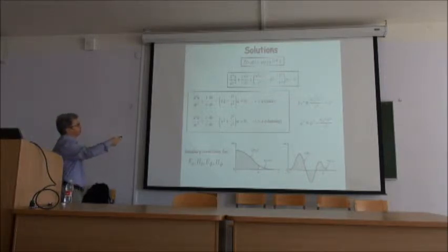And in this equation, if I look at these two components, inside the core or outside in the cladding, we see that this number is going to be positive inside the core, and I define that quantity here, which is just the difference between these two terms. Outside, these two terms will be negative, so I actually define it as the reverse, as this alpha squared. Then I use those variables here instead of those, and I have a slightly different equation. Please note that in this part I have a plus here and a negative on the other side.